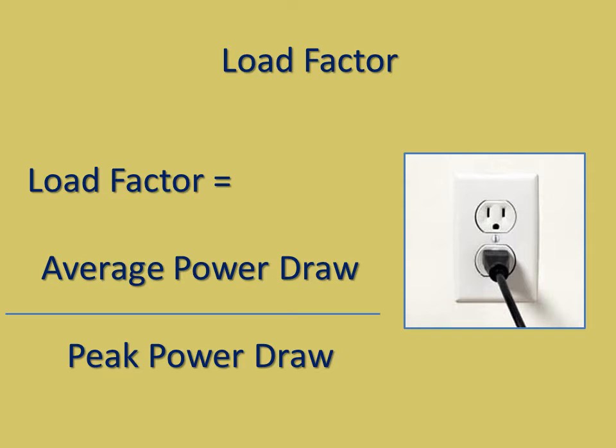So the same kind of concept is you have to build the infrastructure for electric power production and generation to meet the peak demand. However, we know most of the year that demand for power will not be equal to the peak. It'll be the average demand. And so this load factor of 40-50% is an important statistic that we can look at, kind of the efficiency of the overall system in terms of infrastructure and delivery of energy.